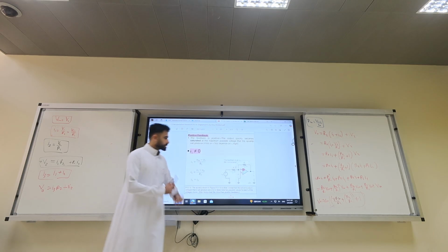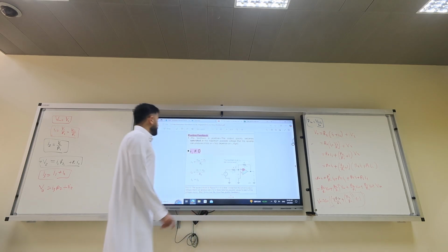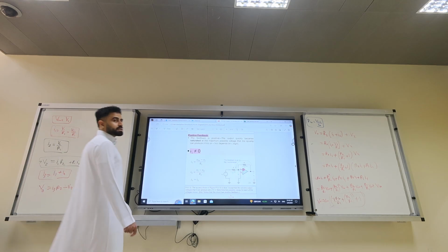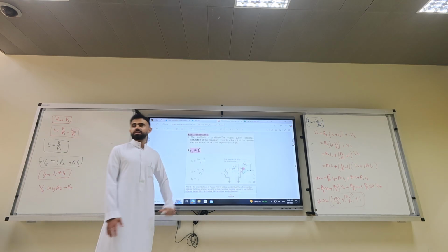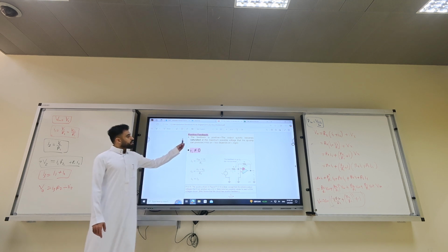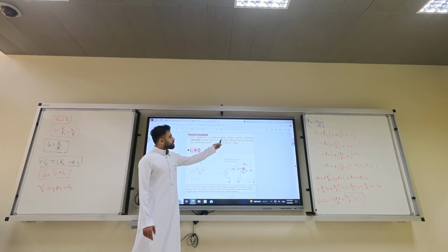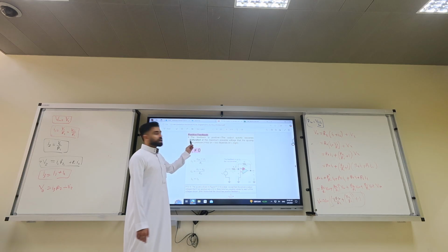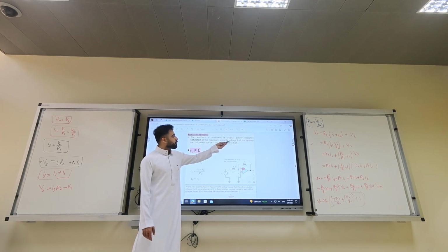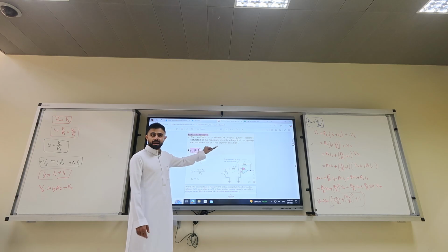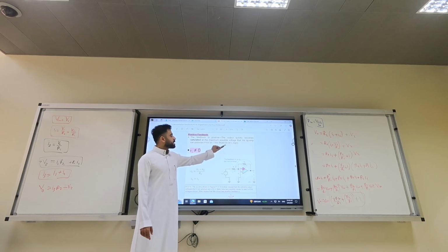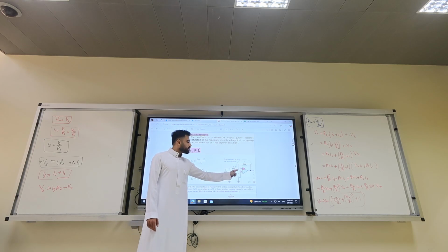Positive feedback. I would end with this slide, and then next slide we will warm up with this, but we hate positive feedback, okay? Because when the feedback is positive, the output quickly becomes saturated, at the maximum possible voltage that the op-amp can produce, either plus VCC, plus 10, plus 5, or minus VCC, minus 10 or minus 5, depending on the sign.